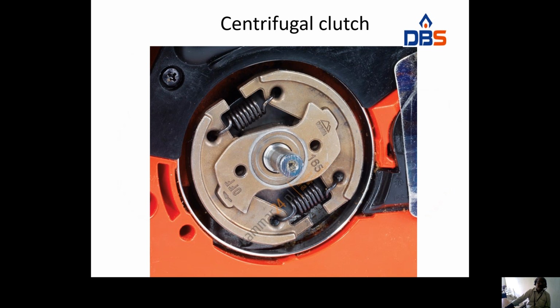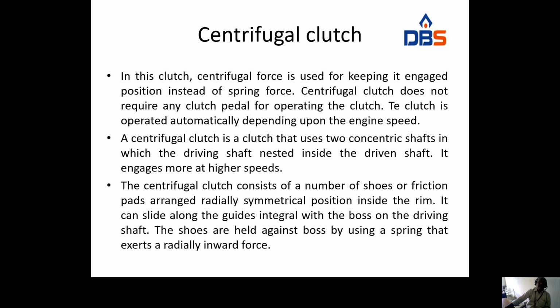Generally we use this in scooters and mopeds. When the speed increases, it moves towards the outer shaft, and like this the clutch is engaged. In this clutch, the centrifugal force is used for keeping it in the engaged position instead of spring force. A centrifugal clutch does not require any clutch pedal. Without the clutch pedal, we can operate this clutch.